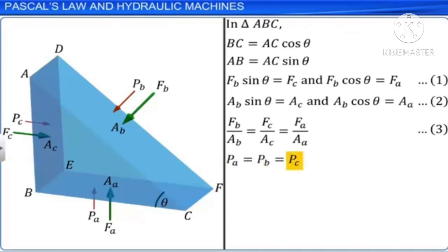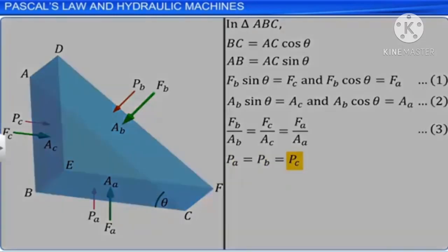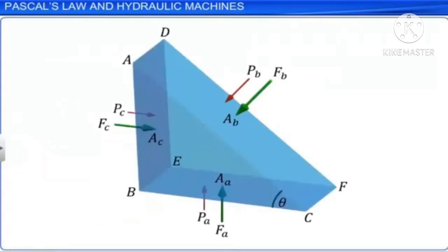The pressure exerted at a point by a fluid at rest is equal in all directions. Hence, pressure is a scalar even though it is in the ratio of force, which is in general a vector, to area.